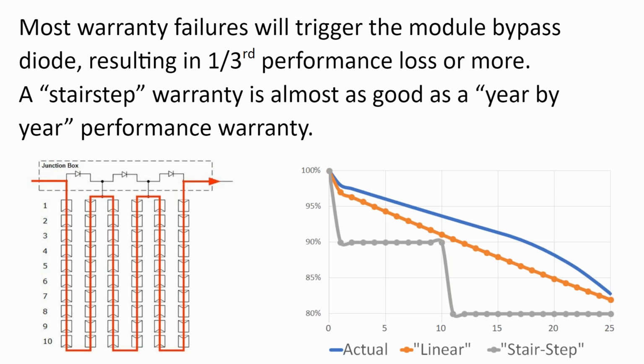Or you're unpacking them out of the box and then putting them onto a lift to lift them up onto the roof, and you jerk the lift and the panels bounce up and down, and if they're loosely stacked, I've seen a bolt get underneath a panel frame, and then the panel frame get jerked up and down, and it pushed down onto the panel and shattered the glass. Usually it's going to be something like that rather than putting weight on the surface itself.